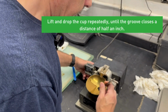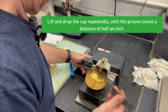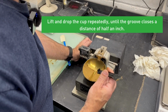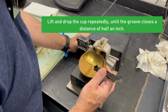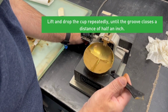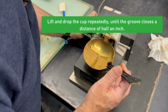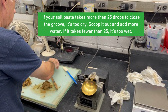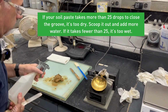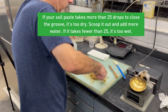From overhead, this is kind of a guessing game with the moisture. I want to look between 25 and 35 blows for this first one, and we're a little on the dry side, I think. You know that because the gap hasn't quite closed. It hasn't quite flowed like we want. So I'm going to stop it, go back to the sample and add a little water to it. Just a couple sprays, and get that incorporated.